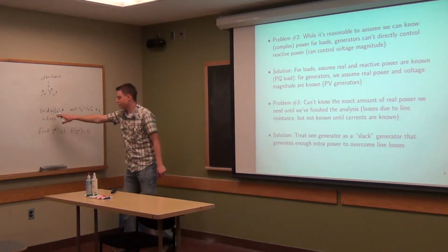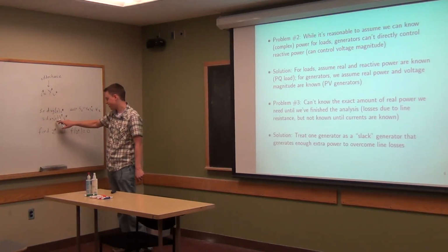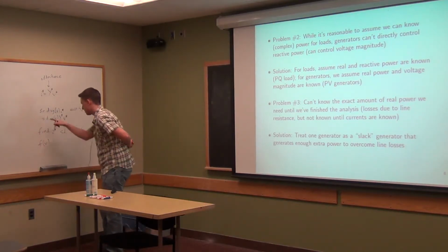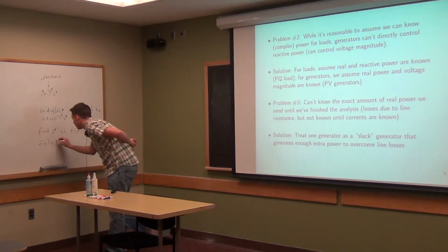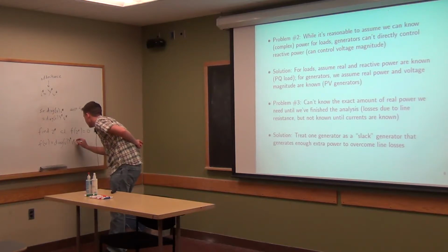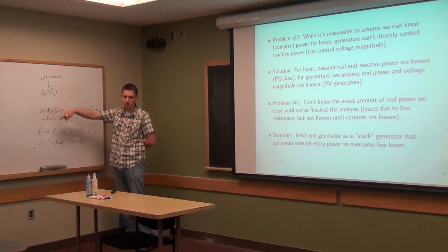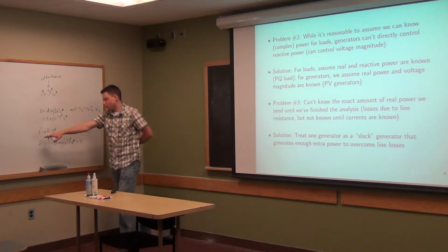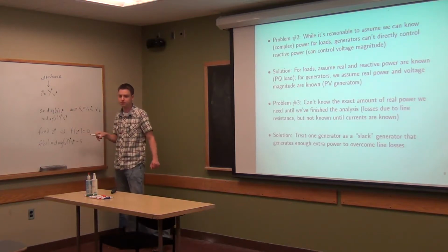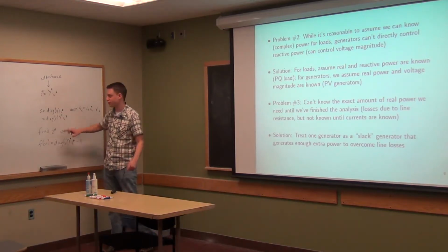But just to see how this applies here, remember, our variable is v. And so we'll define f of v just to be the difference between these two things. So f of v is just going to equal diag v y conjugate v conjugate minus s. And so a 0 of this function is obviously a situation where this is in fact equal. Just making it clear how Newton's method for finding zeros translates into a method for solving this equation. Right, so if you find v such that this thing equals 0, then you found v such that this equation holds.